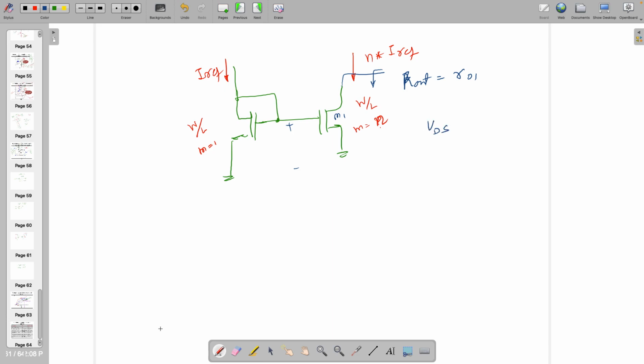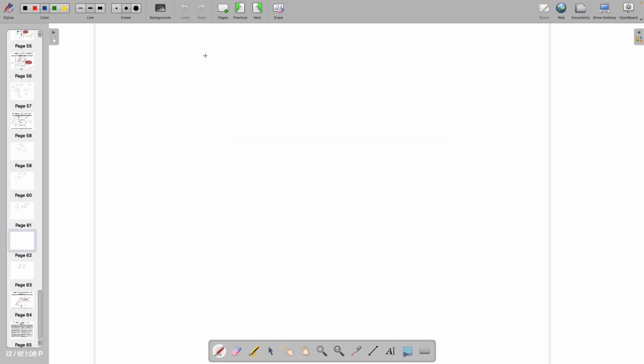Similar things you can find out for other topologies, if it is cascode, triple cascode, and so on and so forth, if you have enough headroom available. By the way, do we understand this word headroom? If you have enough headroom available, that is VDS values, then you can go for it. Same way legroom also, right? Zero side legroom. So if you have enough headroom available, then you can apply the required voltages or the required topology, and you can work on it, right?